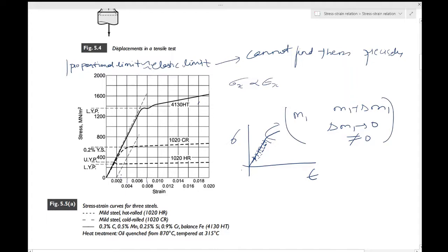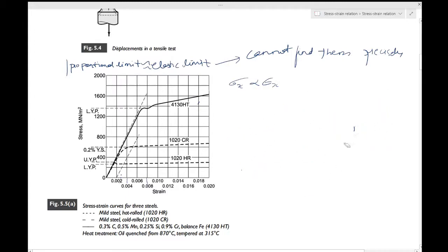But in an experimental analysis, as I have said, it's not precise. Now, why is the elastic limit not precisely defined? Again, it deals with the limiting case of no permanent set, meaning you do not get a permanent strain, and that's where you want to say your elastic limit is.